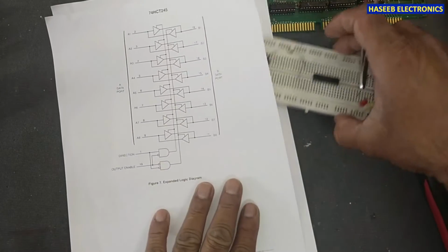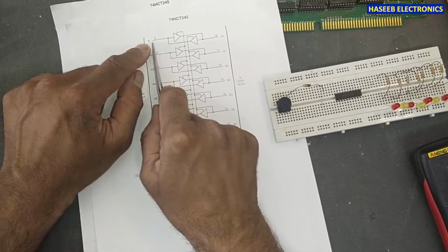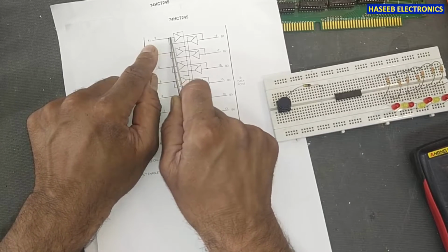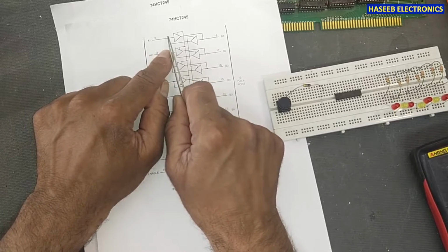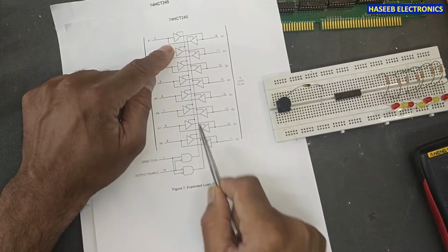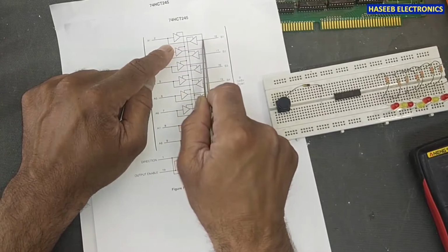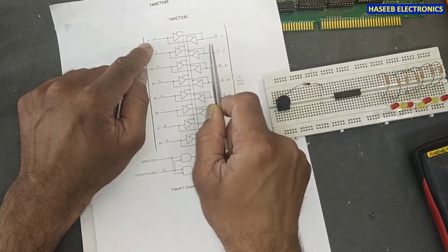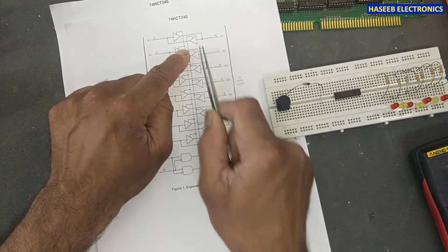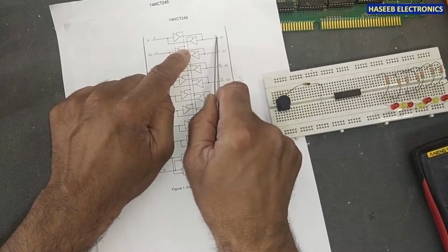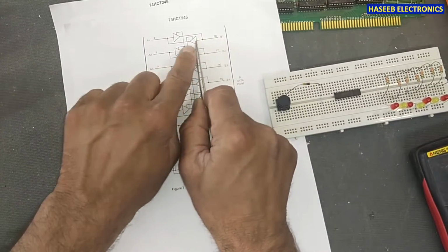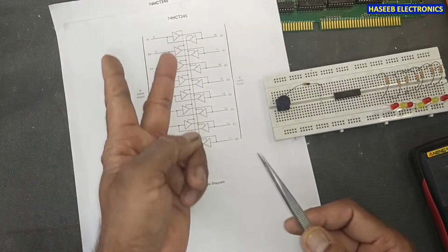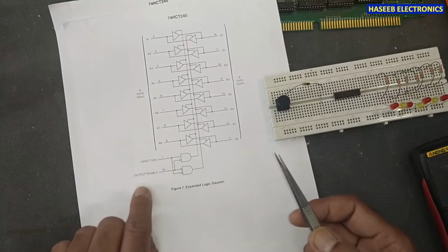If we see its logic diagram, this is pin A. We will see one module, port A, pin number 2. It has a buffer here that is called a driver. When this pin is enabled, at that time it will give output to port B from here to here. And when this is enabled, this is called the read and write function. At that time, pin 18 will be input and pin 2 will be output. So the role of the pins will be reversible by using these two commands, direction and output enable.